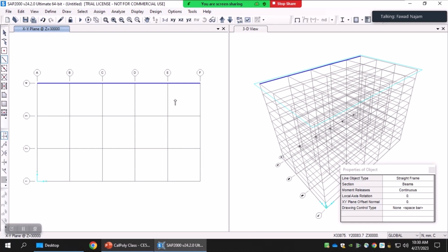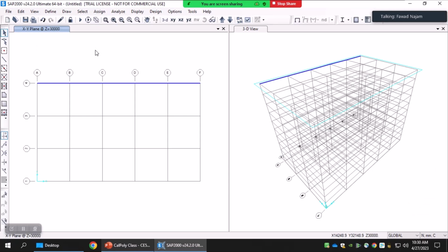And if I right click at a particular location, the continuous beam drawing option will end, but I am still in that drawing mode shown by the cursor symbol, unless I again click on this arrow button, and now I go out of that drawing mode, right? So please play with these options later on, how you can draw or create geometry of your structure using these grid lines.